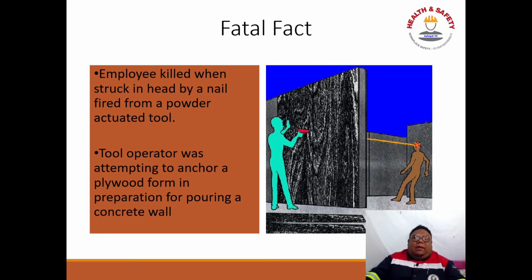But based on my past experience, I allow power actuated tools only on mechanical work, in the channel, because putting bolts in the channel sometimes needs this, and also heavy wall type concrete work we allow. But for other types of activity, no, we do not give approval. That's why most of the power actuated equipment here is only in the warehouse. Okay, next.